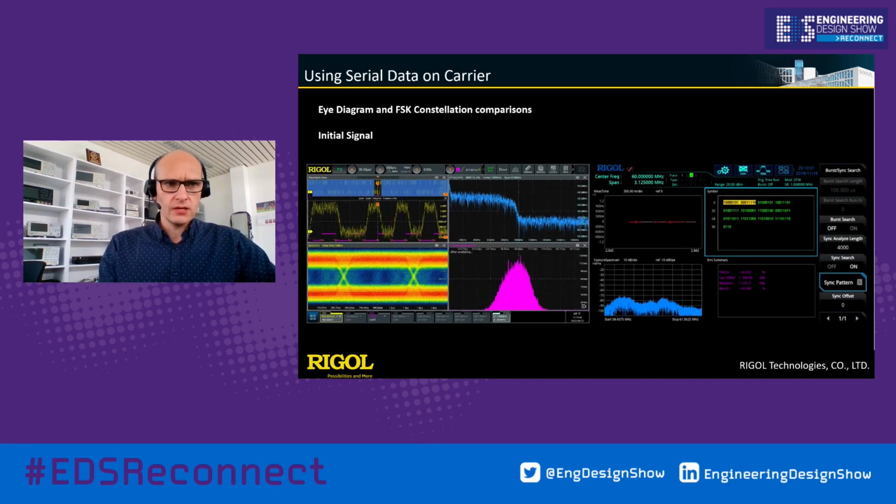And here again, you can see, for example, a signal which is disturbed and not optimized. You can see the constellation diagram looks quite bad. The errors are quite bad also in the vector signal analyzer mode. And this is the result of the problems we have on the digital side.